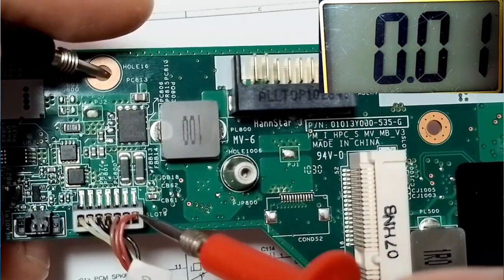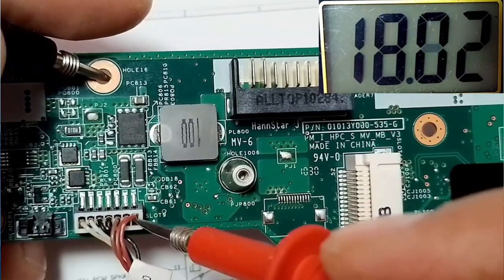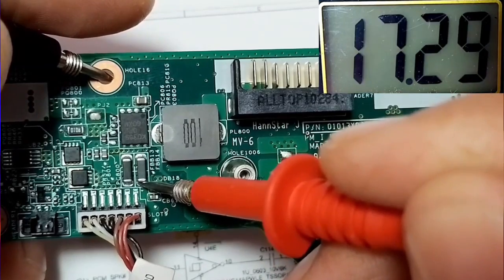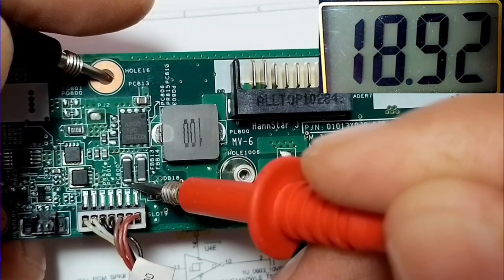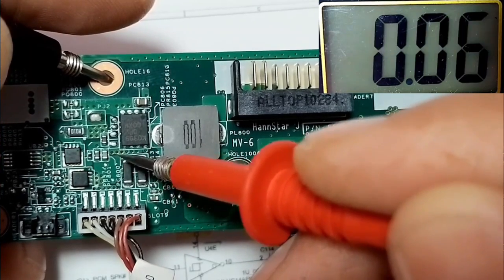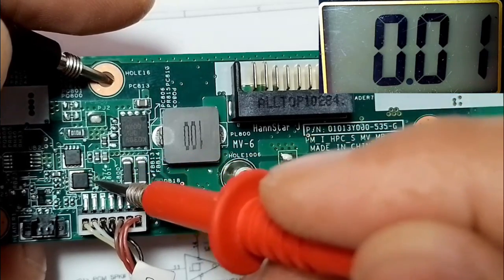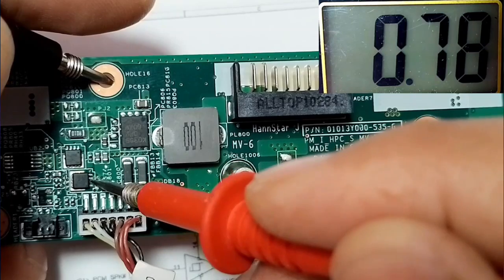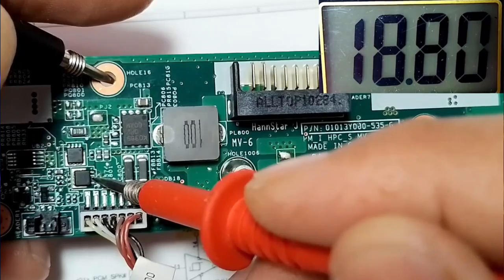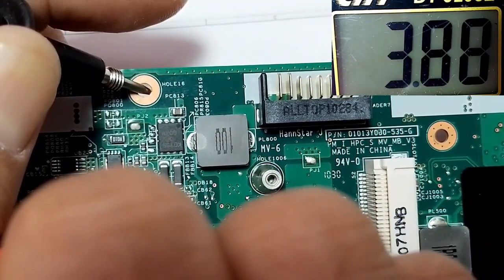So basically this is the 19 volt part here. Okay, so here we have 19 volt, then it goes directly to this inductor and also this inductor, and then goes to the other side of this inductor and also this inductor, and then it goes directly here to this power MOSFET, as you can see. So here basically this is the source of the MOSFET, we have 19 volt, and here we have the drain, we have also 19 volt, as you can see.